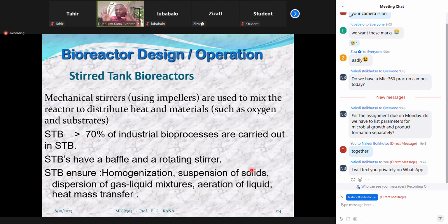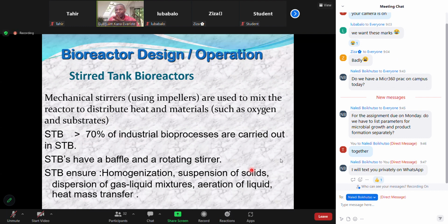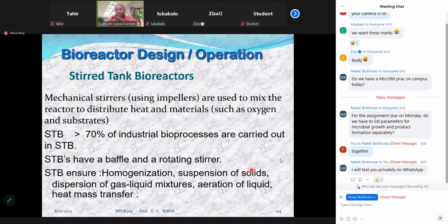It's the entire mixture of your carbon source, which could be sugarcane molasses or other starchy material, then your nitrogen source, which could be corn steep liquor or yeast extract, and the different mineral salts required for growth, that need to be mixed in that first tank in the right proportion before it undergoes sterilization. This is basically what takes place there: mixing the right proportion of each ingredient and subjecting it to sterilization.